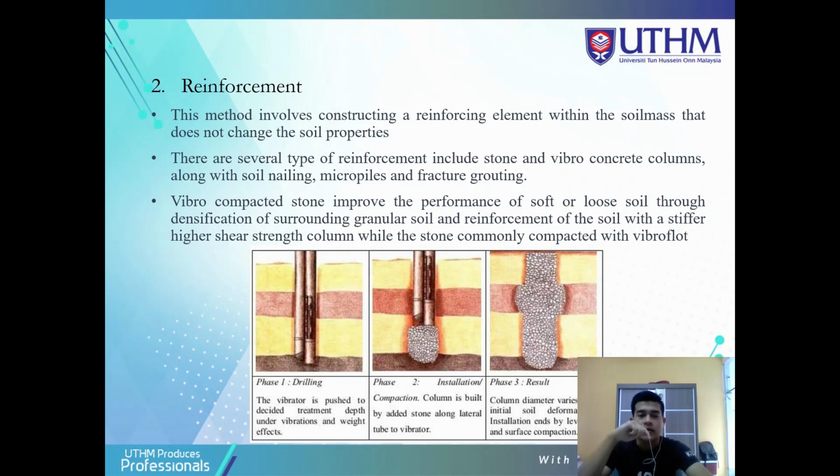Then the vibrator is raised several feet and the stone falls around the vibroflot, filling the cavity that has been formed. The vibrator is repeatedly raised and lowered in this fashion, compacting and displacing the stone in 2 or 3 foot lifts. Lastly, the flushing water is directed to a settlement pond where suspended soil fines settle.